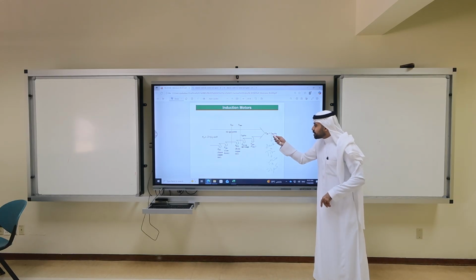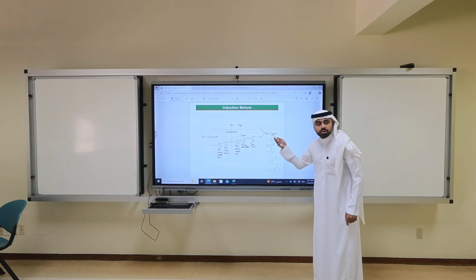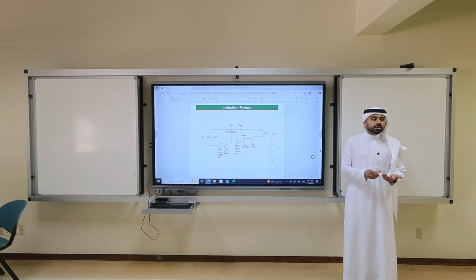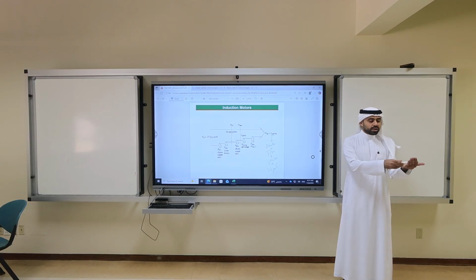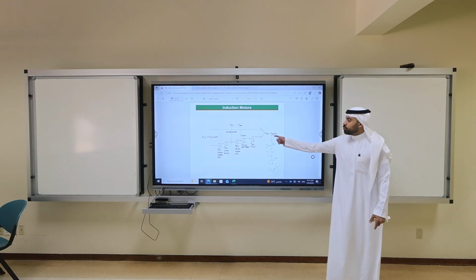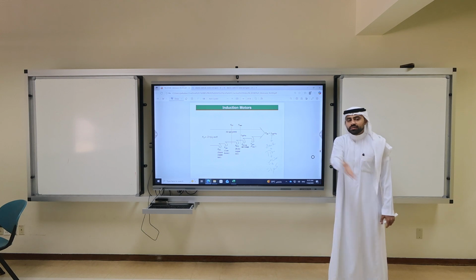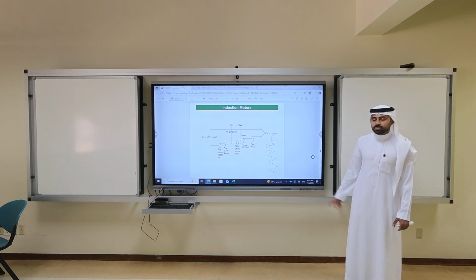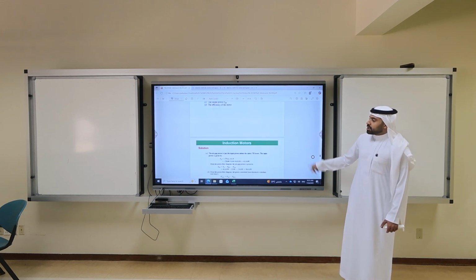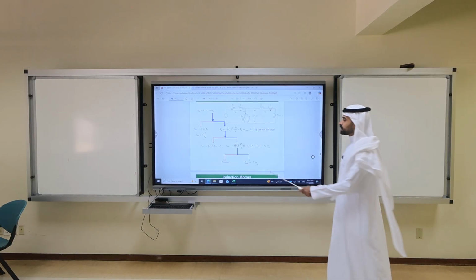What you need to know is that the induced torque should be larger than the load. Otherwise cogging will happen and it ends. The motor tries to rotate but cannot move. What if it is not at the same speed? If it is not the same speed, if the load is heavier than the induced torque. Okay. Keep in mind these equations. These are the equations.